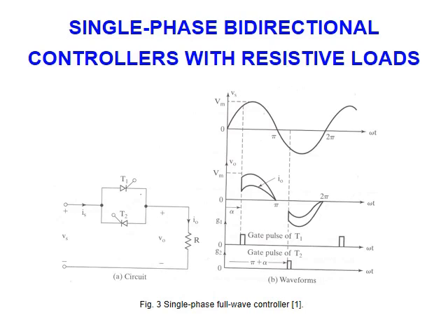There is no diode, just two switches, switch 1 and switch 2, connected anti-parallel. Now you can see this is the input. See the output: this half is conducted by T1 and this half is conducted by T2. They start at alpha, and here at pi plus alpha, right?